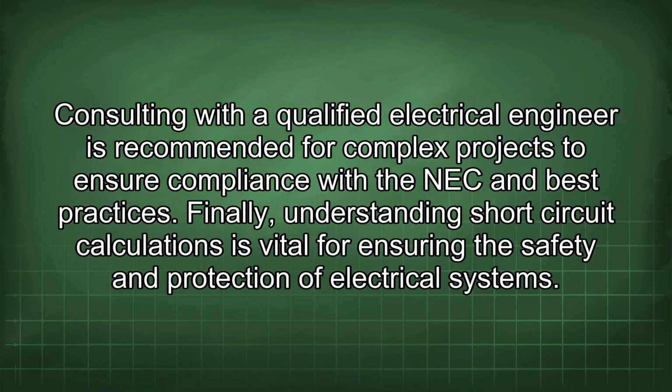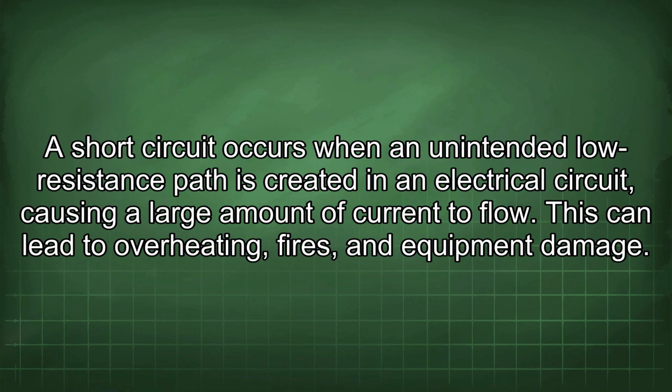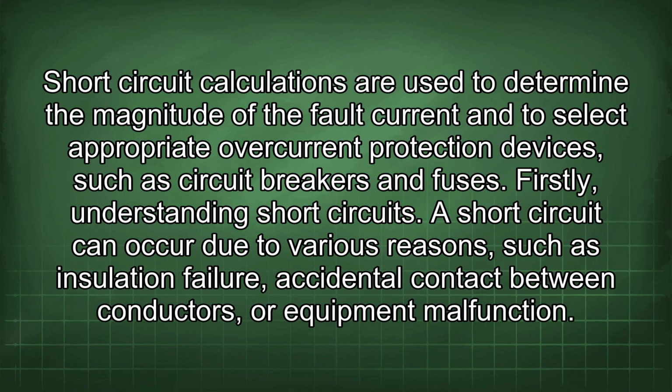Finally, understanding short-circuit calculations is vital for ensuring the safety and protection of electrical systems. A short circuit occurs when an unintended low-resistance path is created in an electrical circuit, causing a large amount of current to flow. This can lead to overheating, fires, and equipment damage. Short-circuit calculations are used to determine the magnitude of the fault current and to select appropriate overcurrent protection devices, such as circuit breakers and fuses.